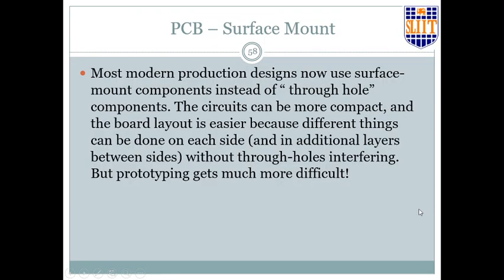And also, with the previous technique that we were talking about, you can't use surface mount devices. And also, you can't have multi-layers in the circuit. But in PCBs, they have developed techniques to have multiple layers, sometimes 3-4 layers in between. Right? Motherboards and so on usually use one of the layers for power, one of the layers for ground. So shading techniques can be there, and you can print any detail. Most of the time, there are situations where you print antennas, inductors on the PCB routings themselves.